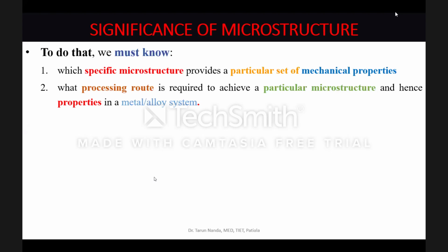Similarly, strength, the resistance to deformation under external gradual load, impact strength, the resistance to fracture under sudden or jerky or instant load. Ductility, the amount of plastic deformation which a material suffers on the application of external gradual load. So any property for which, to determine the magnitude, you have to put a load or stress over the material, and the material's behavior under that stress or load gets you that property, any such property is called a mechanical property.